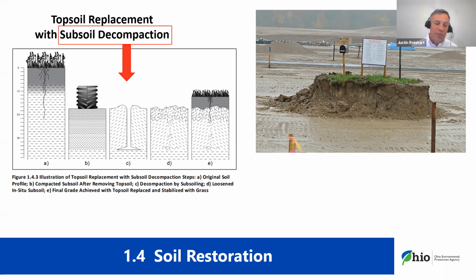There's sort of an expectation with the impervious surface disconnections that it's sort of unpoliceable. These areas may move with time. You can't prevent people from building a deck or swimming pool. Doesn't mean that water's not going to eventually have other grass to go to. But there's sort of an expectation. There's a win loss that probably will occur, and there's so much to be gained that we really can't put those stipulations on it. But the grass filter strips, a little bit less of an issue because they're maintained as a pervious area, but the conservation area should be somehow protected.